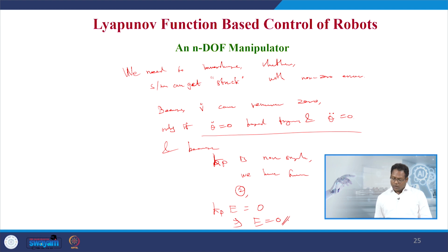Thus, for the control law given by equation 2, we can state that it can globally stabilize the system. So, we can say that the system is asymptotically stable with that controller given by equation 2 and Kp. This conclusion comes from the closed loop dynamic equation, that is equation 3, not 2.